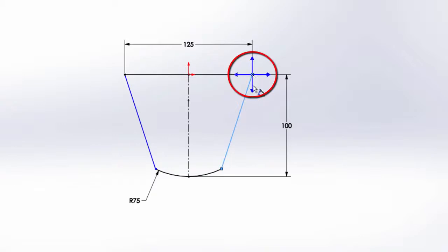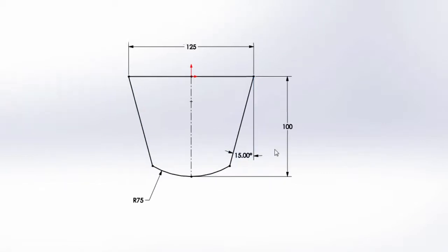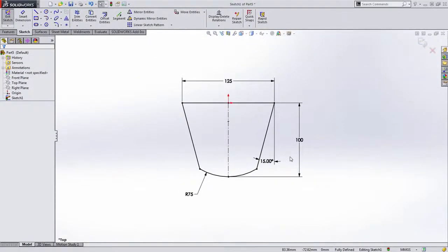with a quadrant selection, specifically for dimensioning angles. If you choose the arrow in the direction you want to place the angle, SOLIDWORKS allows you to place that without having a piece of geometry there. That's really convenient in cases such as this. Now we've got our profile, but if you remember, this is actually extruded up to a radius. So how are we going to do this?